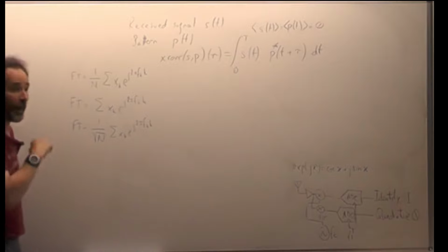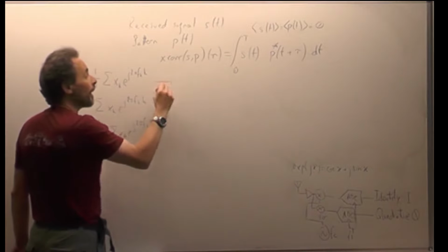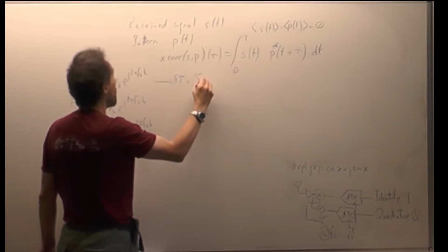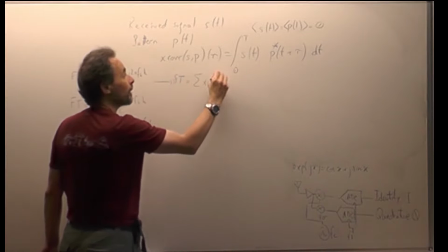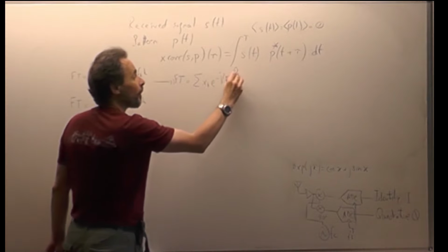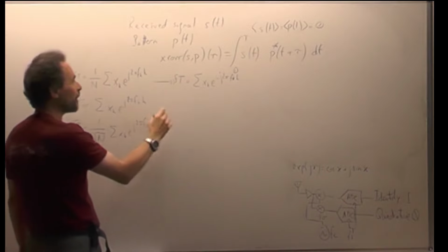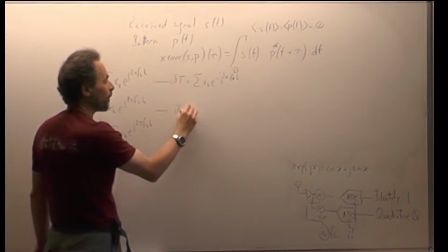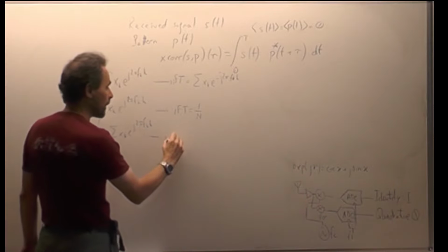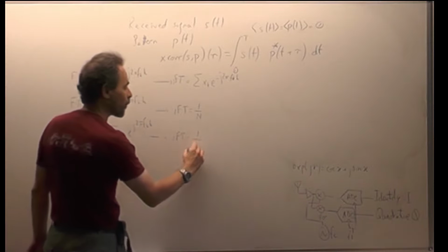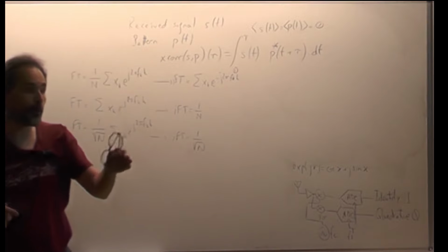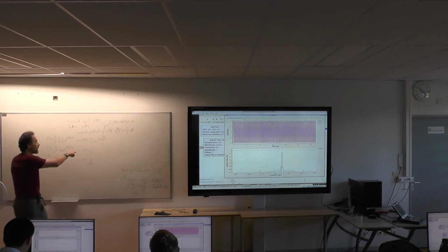The only thing that matters is that when you then take the inverse Fourier transform, in this case it would be the sum of xk exponential of minus j 2 pi fk k. I'm not going to write all of them. In this case, your inverse Fourier transform is where you would put the 1 over n over here. And in this case, you would put in the inverse Fourier transform the 1 over square root of n over here. So you have to be careful whether you're working with MATLAB, NumPy, or GNU Radio, your normalization will not always be the same.